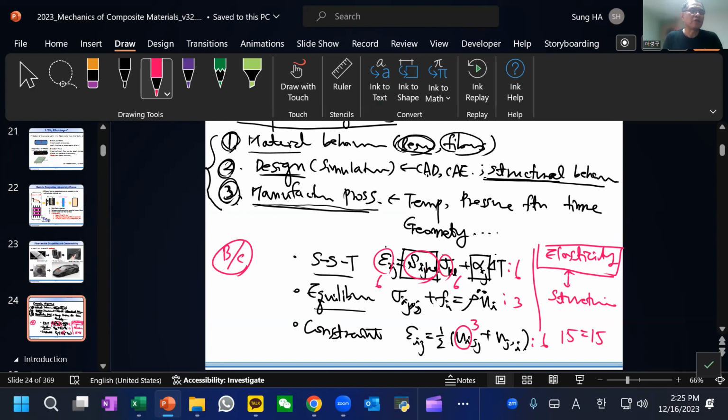Of course, the geometry, right? So always when you solve the FEM or whatever, make sure you got the right geometry and the right boundary condition. A boundary condition can be a displacement or a force, two types, and then a material property. Always three concepts: geometry, boundary condition, and material property. So make sure you got all the right properties specified in defining problems.